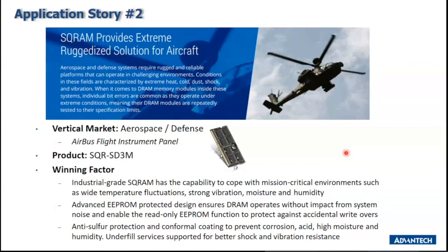Our advanced EEPROM protected design also ensures DRAM operates without impact from other system noise. And it can also enable the read-only EEPROM function to protect against accidental overwrites. Then we also provide customizations for anti-sulfur protection, and conformal coating to prevent corrosion, acid, high moisture, and humidity. And the same goes for underfill services, supported for better shock and vibration resistance.